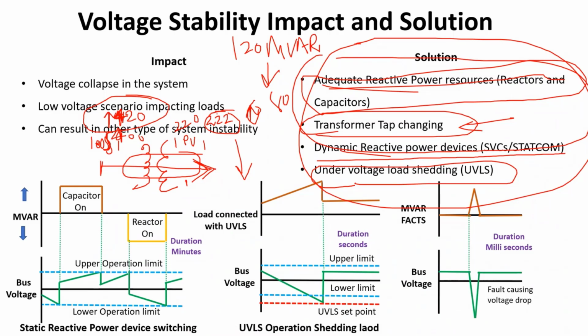That is an additional flexibility that an operator has, not as a part of direct planning. It is a flexibility that I have, that these generators are there which can provide me reactive power support. But if you ask me how you are controlling, these are the basic mechanisms. The problem is that we generally rely on the generator to provide all the reactive power support. Then this becomes a very big challenge for system operation.